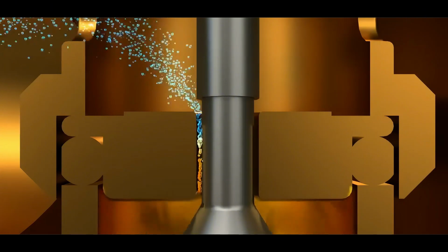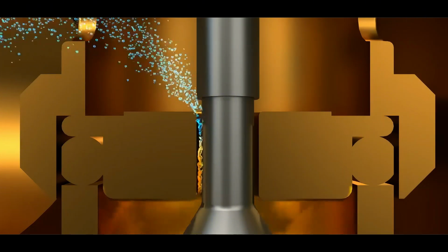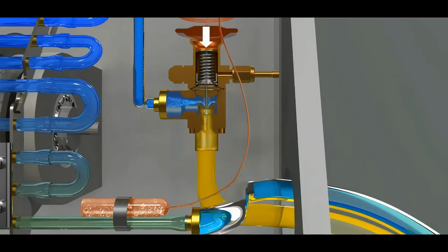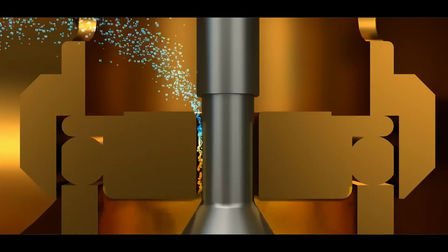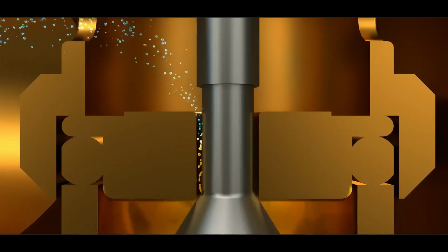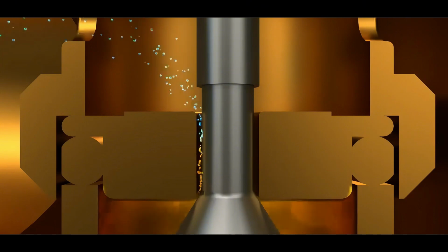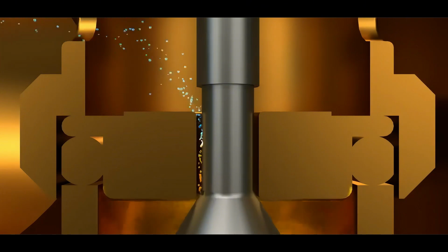When the amount of refrigerant going into the evaporator surges, cooling emission surges too. When the temperature at the exit of an evaporator drops, gas pressure drops, and the amount of refrigerant going into the evaporator in turn drops too. Applying the above principle, an air conditioner controls the amount of refrigerant injected into an evaporator to prevent overcooling.